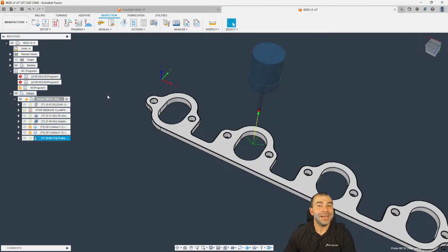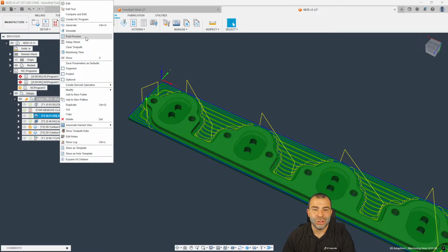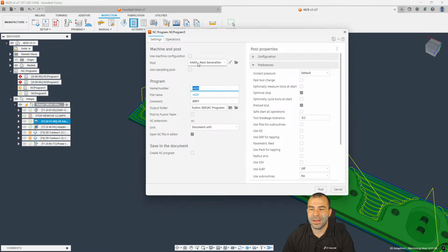But yeah, so on your machine, Deep Thinker, I actually covered this. We can put smoothing at the toolpath level and set everything up that way. But you can also edit your post, right? So there's a lot of different ways to do smoothing. Now, the way that we showed this in our video depends on your actual post processor, which yours sounds like it has, which is great.